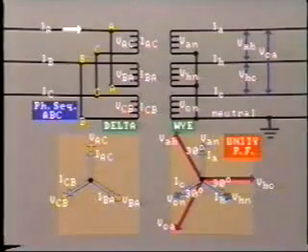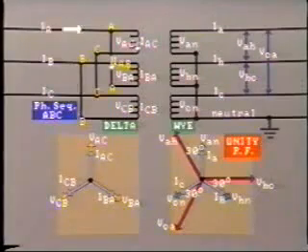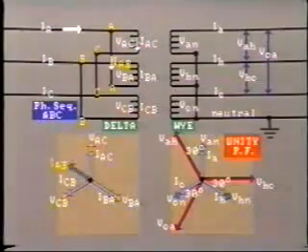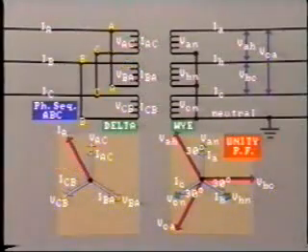Well, look, clearly the line current IA is the sum of the phase currents IAC and IAB, which is the reverse of IBA. Therefore, plot IAB on the phasor diagram and add IAC, which gives IA.